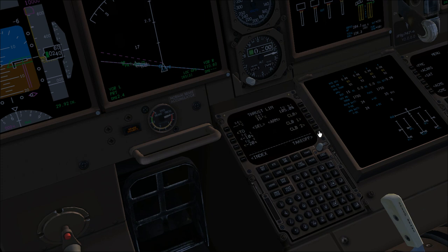We can now go to the thrust limit. Today we have a long runway and a low weight, so we can use a derate. And actually we will use takeoff 2, the rated takeoff 2. I know actually that with a contaminated runway we should not use the selected temperature anyway. We just think to have rain today, and so we can use it.